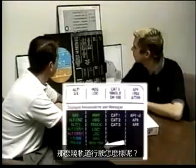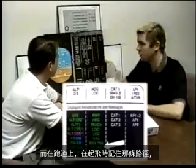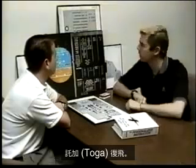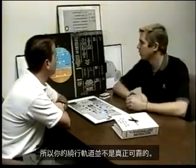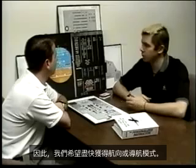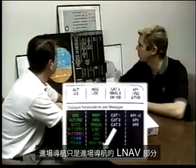What about go-around track? Go-around track's basically a similar thing as a runway track, whereas on the runway track during takeoff it memorized that path. Go-around track has memorized the last path that we took before we selected TOGA on the missed approach. Go-around track is pretty sloppy because you've got to realize that you're not necessarily flying down the runway path, so your go-around track is not real reliable. So we want to get either heading or nav mode as soon as we can. Approach nav? Approach nav is just the LNAV portion of the approach nav approach has been engaged.